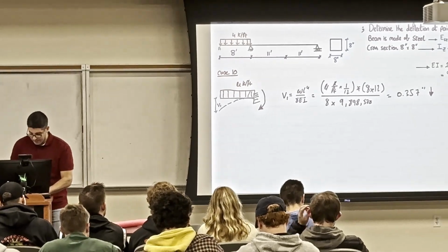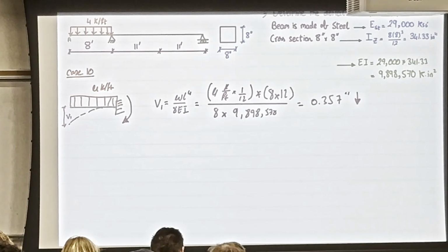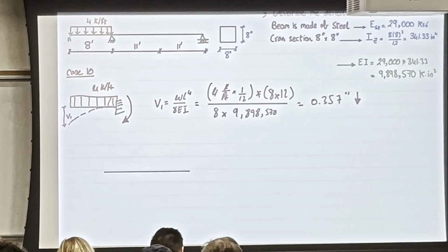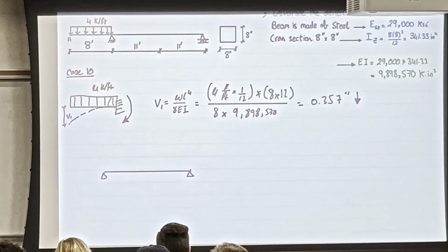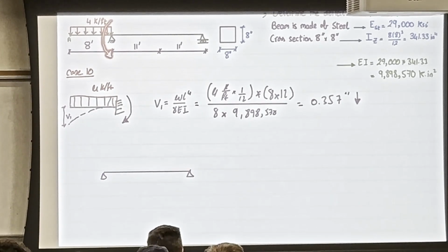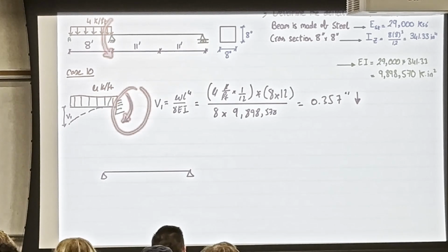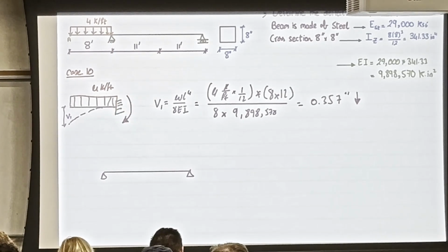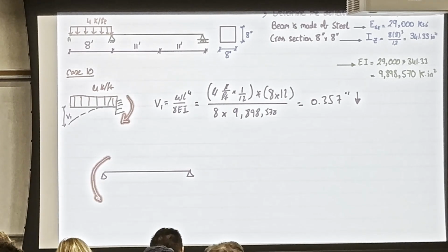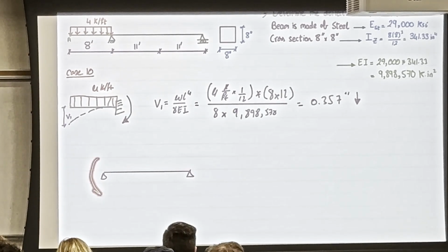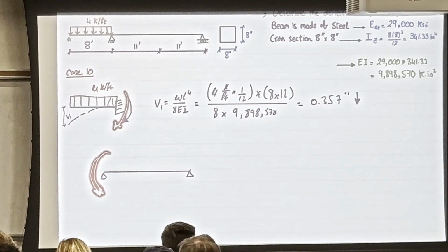So what I'm going to propose now, I'm going to initiate a load case, which is a correction load case, which takes into consideration this bending moment. What I want to do, I want to find, as if I remove this cantilever, the moment that will come from it, and I'll be putting it here. So that this bending moment, it is counterclockwise, it's gonna cancel that one, which is clockwise. So this is the reaction. So you can either find this bending moment reaction and just flip it here, or do the opposite direction here, so that when you put this on that, they will cancel each other.